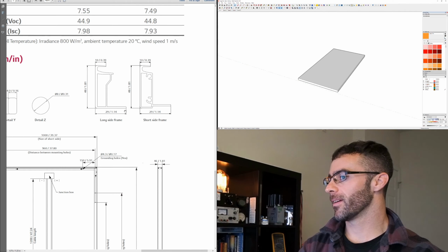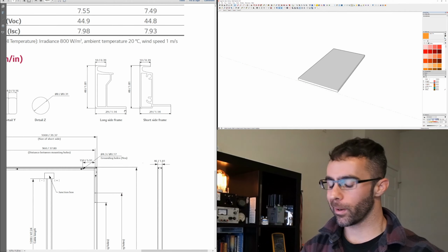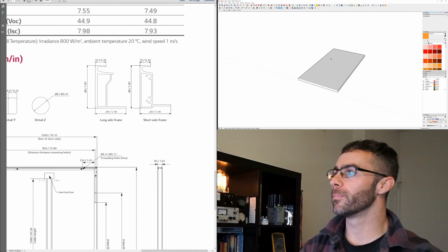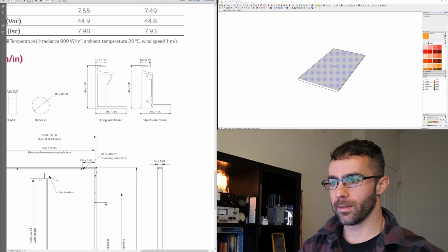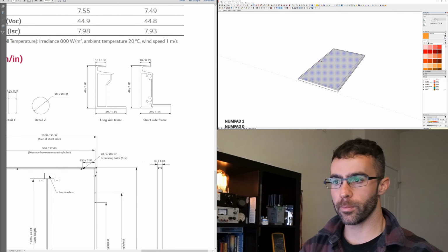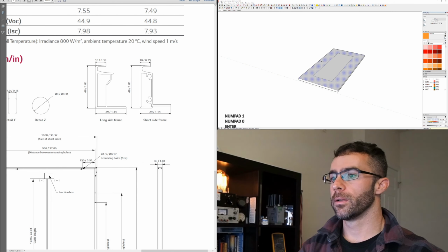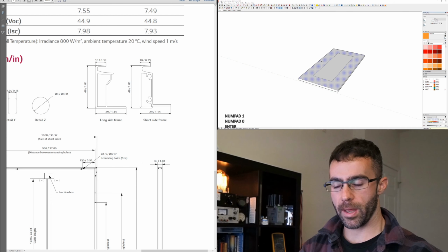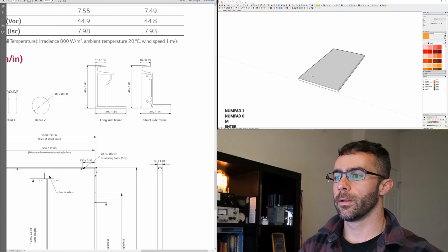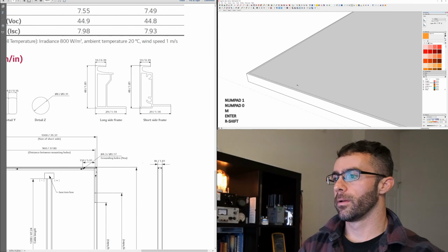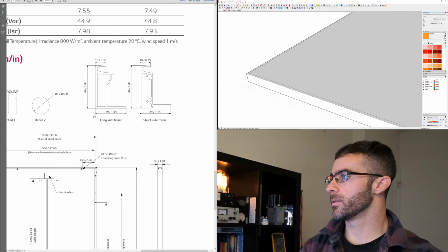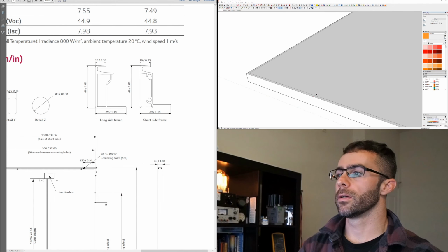If we want to make it slightly more convincing, you can add in this outside rim. That is going to be another offset command, and that rim is 10 millimeters. Oop, I forgot mm, so you can just overwrite that 10 mm. We have that, and the underside 29 millimeters on the inside.